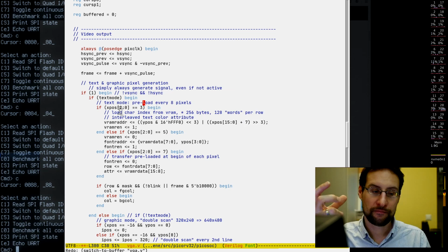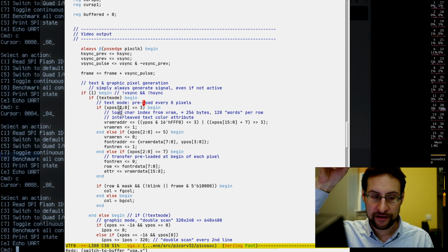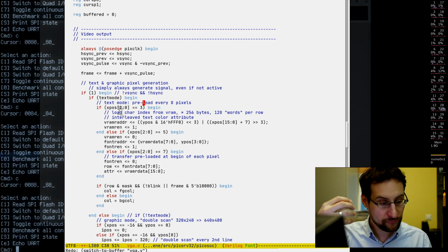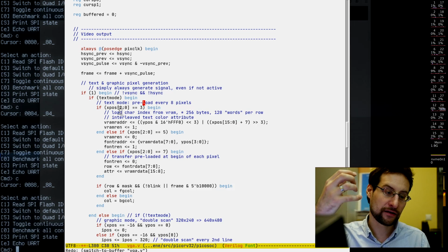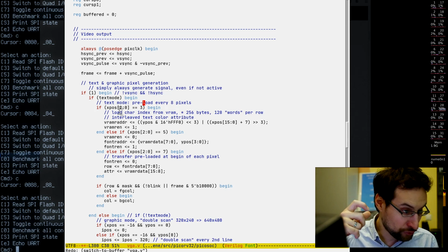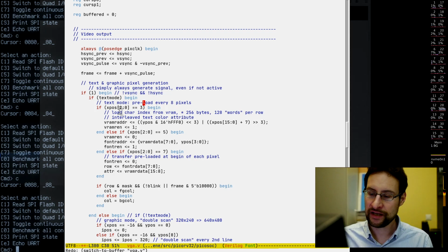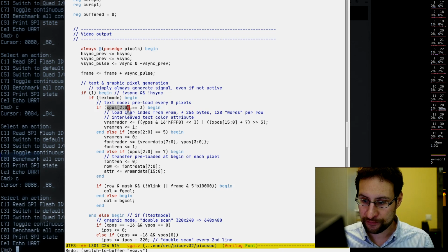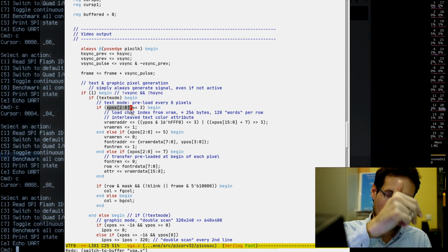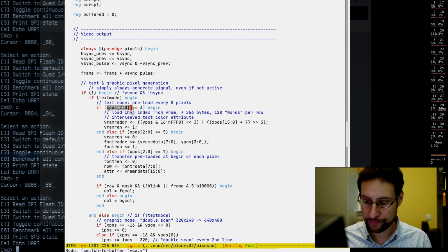I was thinking maybe implementing this differently, like having some pixel pipeline, but in my opinion it would get way more complicated to push the pixels through some kind of pixel pipeline delay, like first in first out. So I opted to rather fix the video timing to give us some negative number for the front porch of the synchronization signal.